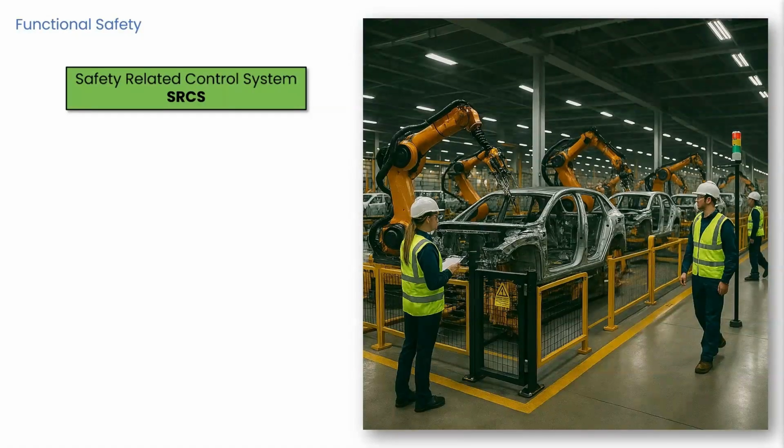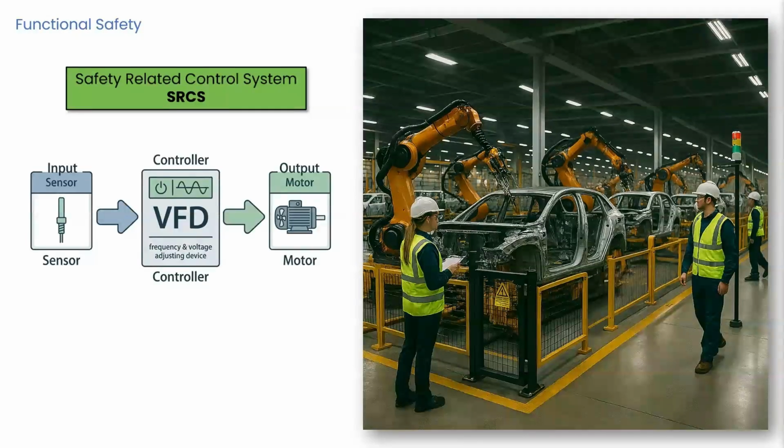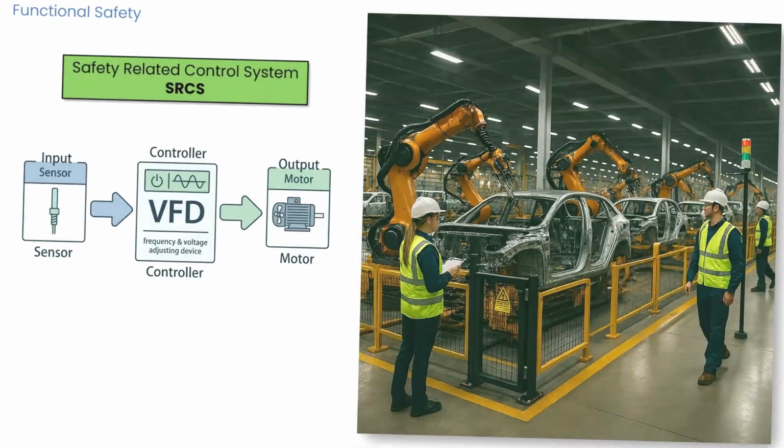Functional safety is the part of the overall safety requirement that depends on the correct functioning of the process or equipment in response to its inputs. For example, an over-temperature protection device using a thermal sensor in the windings of an electric motor to de-energize the motor before it can overheat is an instance of functional safety.